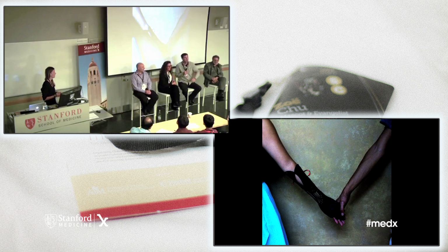And that's actually a very astute question, because since complexity is free, you can not only add the aesthetic attributes that you like, but all kinds of mechanical attributes. So we have something that we coined selective flexure, which means that if you compromise a structure in a certain axis, it will bend a certain way and not another way. So the fracture brace, the black fracture brace you see there, will bend open like a taco, but it can't bend torsionally, which would undermine the efficacy of it as a fracture stabilization brace.